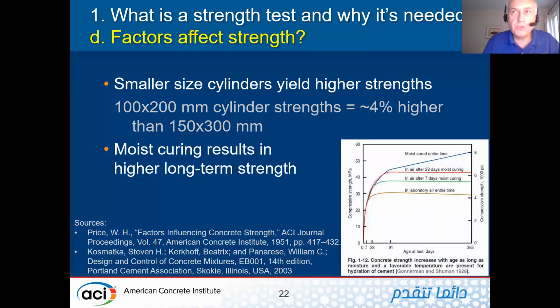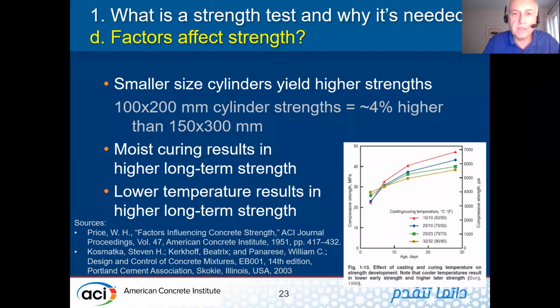When you moist cure the specimens, you can expect higher long-term strength in the specimens that are moist cured all the time. And the same thing when it comes to temperature, the lower temperature will yield higher strength at later ages.